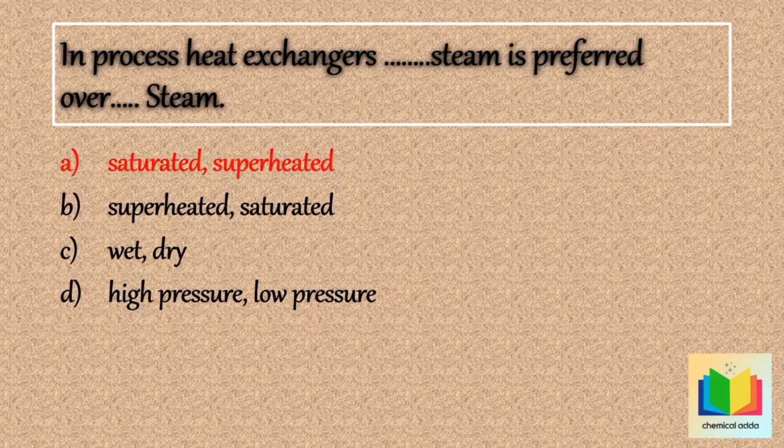So the answer is option A, saturated, superheated. Because the condensing film coefficient of saturated steam is much higher than that of superheated steam.